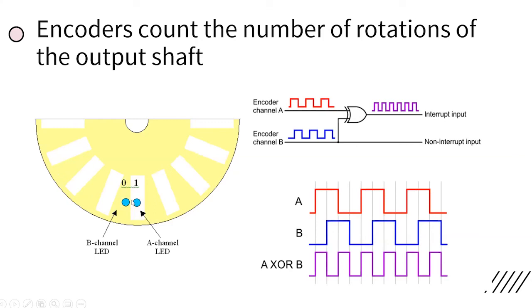Here we see that when there's nothing here, A will turn on, and then when something's in front of it, A will turn off. And the same is true for B. Because this system is rotating clockwise right now, we see that A actually turns on first, and then A will also turn off first. So when you're recording the two step functions you get from this, we see that A is actually leading B. So A turns on first, then turns off first. Because we know that A is starting first, the system's going clockwise.